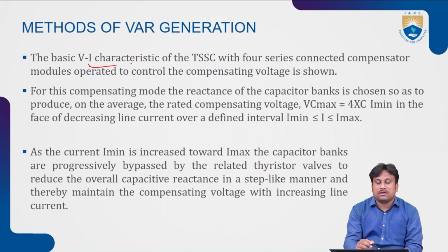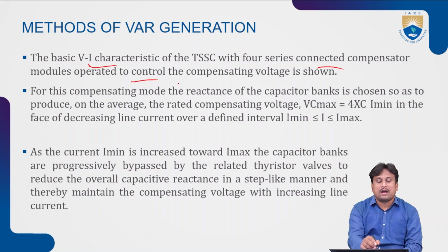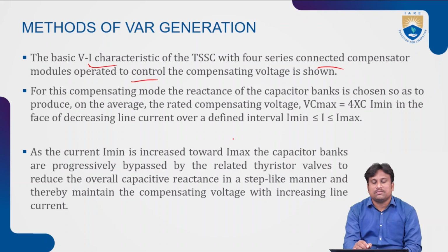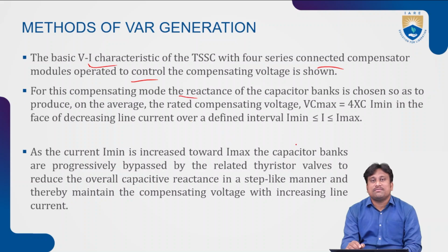Here the characteristic shows a TSSC with four series connected compensator modules operated to control the compensating voltage. For this compensation mode, the reactance of the capacitor bank is selected so that it produces the average rated compensating voltage.